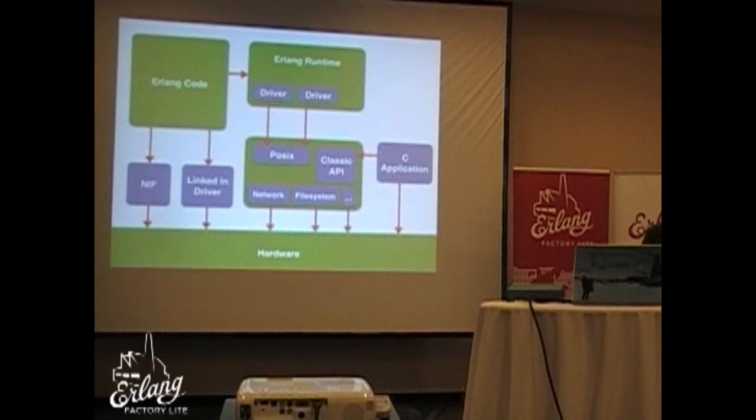And these NIFs and linked-in drivers are nice because you actually get very low-level access to your hardware. If you write some C code or whatever that talks directly to the hardware, there's nothing in between. You're literally alone with the Erlang VM and the C code inside the VM, let's say a NIF or something, and you talk directly to the hardware. And you know when the Erlang VM will be preempted because there are no other processes running on this operating system. If there is an interrupt coming from hardware, you know it will be taken care of in this context directly. So it's easier to do soft or even maybe some hard real-time stuff with this.